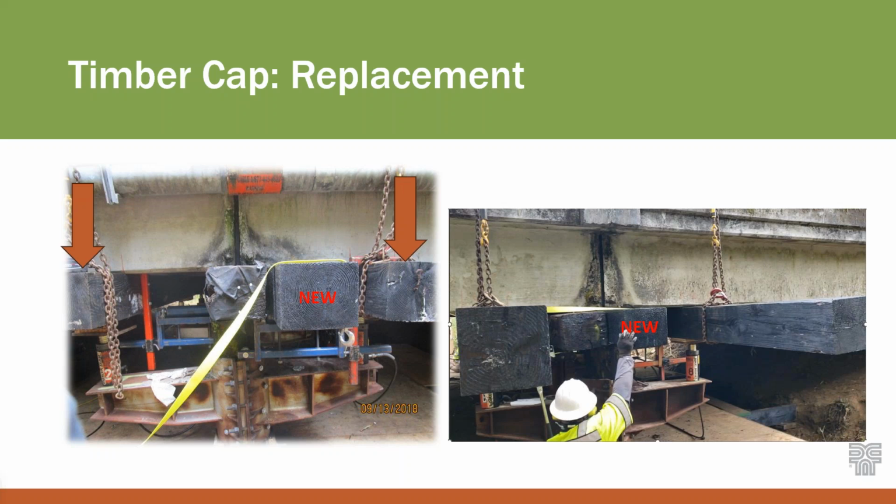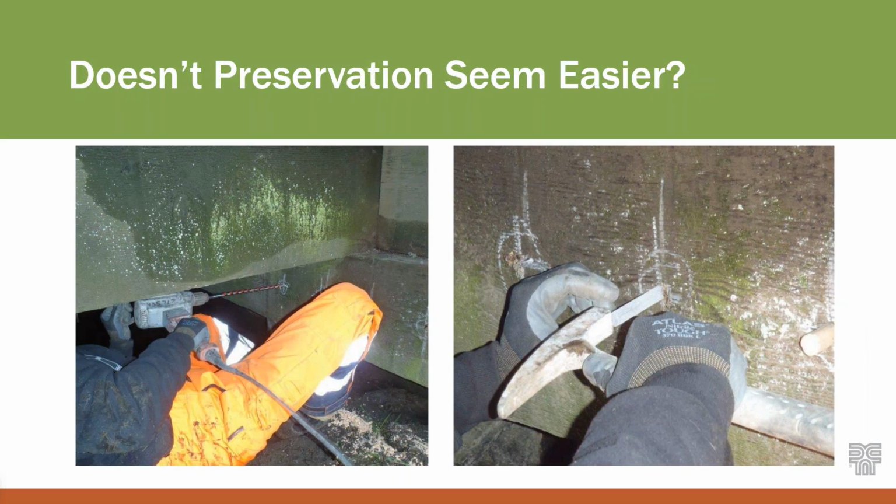But after we went through and looked at what the repairs look like, I wanted to flash back real quick and be like, doesn't preservation seem like a pretty easy option, right? Here's the one worker. He didn't have a lot of clearance in that photo on the left, so it does suck that he's having to lay on his back as he's drilling that hole for the borate rods to go in. But it certainly is a lot less work than jacking the bridge up or bolting channels to it. And there they are, just drilling a hole, tapping the rod in, and then putting the plug in behind it. So that's the desire of this partnership, to help highlight these areas where maybe it could be a little easier.